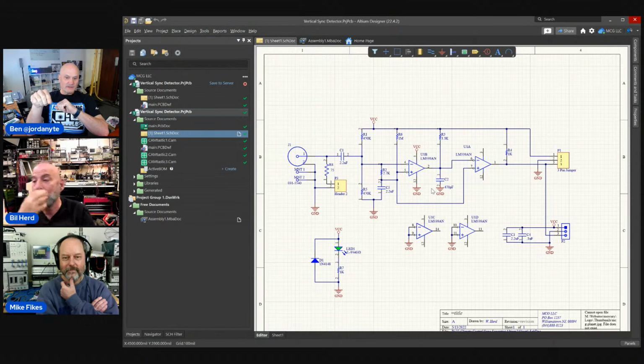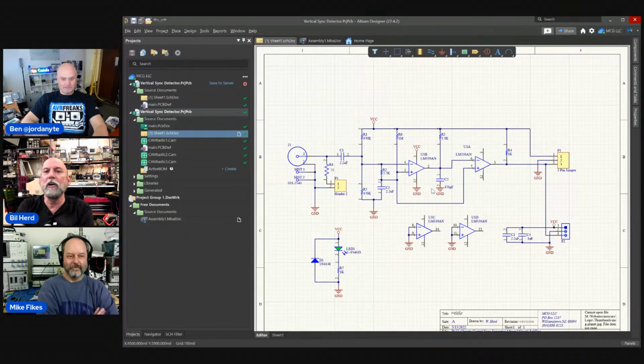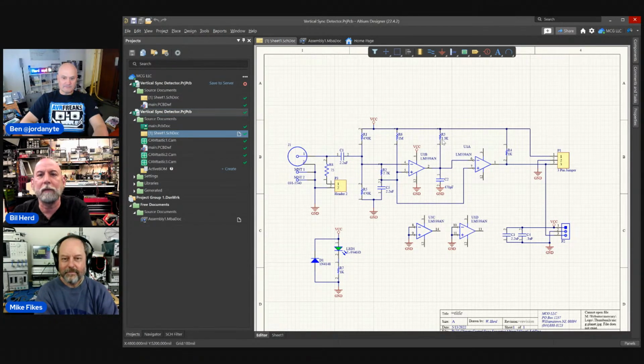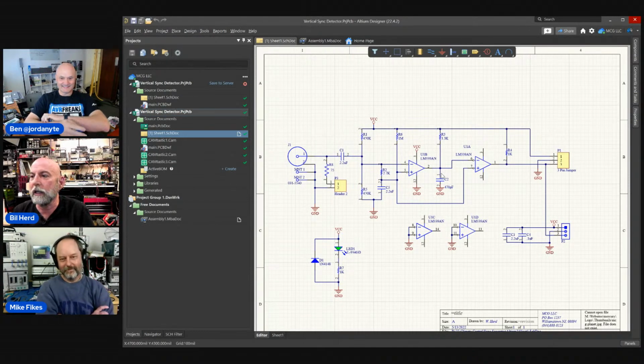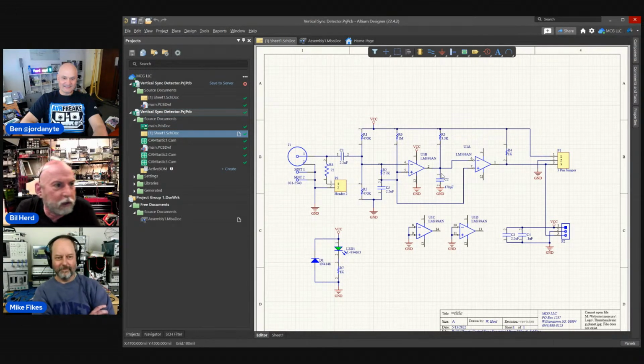Yeah, those are open collector outputs, right? They're 339s, is that right? Yeah, that's correct. It shorts it out, and then RC charges it. So I can pick this RC time constant to turn it into about a 4 microsecond pulse. That's the second part of this, the magic juju of an LM339 circuit like this: you use the open collector for everything it's worth. You can actually do audio detection with it, all kinds of things. But I slam it to ground, low impedance, and let it drift high under R, whatever R that is, R3.